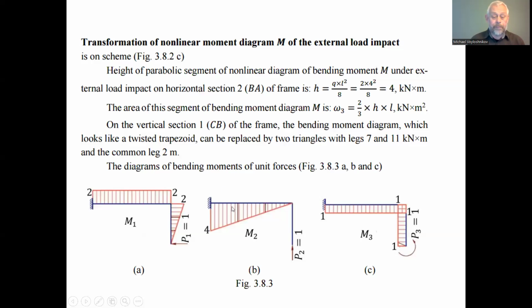We have to have the bending moment diagrams under the action of the forces applied horizontally to the point C, applied vertically to the point C, and the bending moment. The bending moment, if applied at any point, has its diagram distributed to all points of the mechanical system. So this is easy because it is assigned the bending moment equal to 1. This is one of 3 efforts in the directions of finding the displacements of the point C of the mechanical system. So we use this diagram as one magnitude under the action of the unit moment.